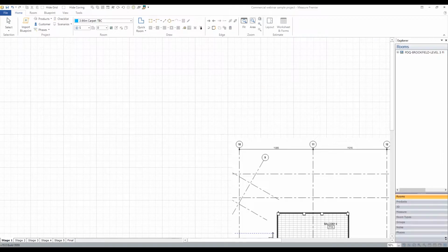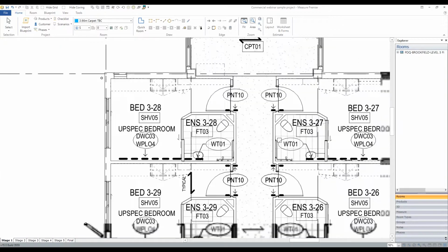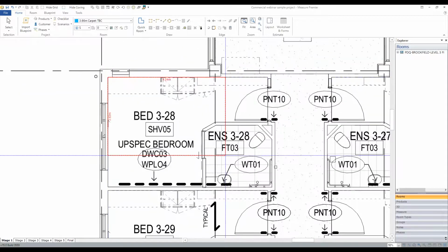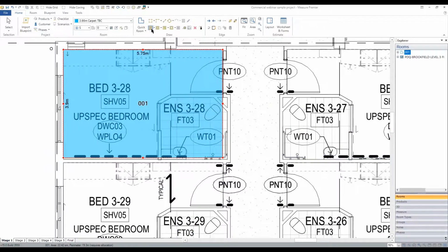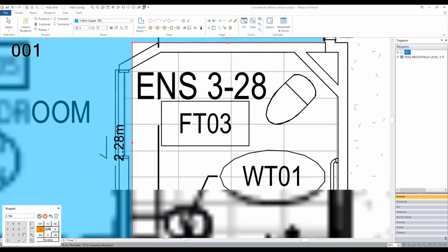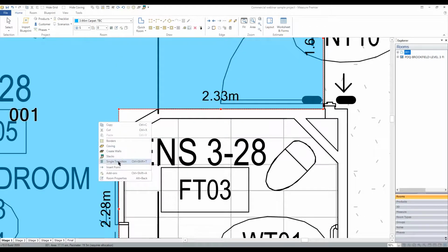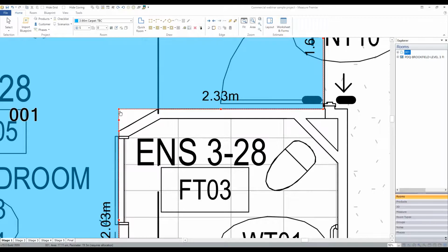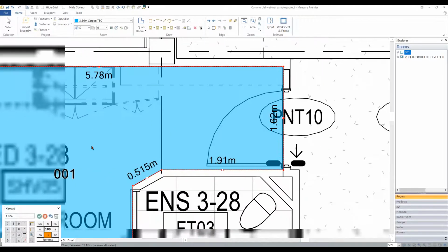So with all of our products created, I'm going to go ahead and start drawing up these rooms. We won't worry about what product is going into the rooms initially. We'll deal with that in a moment. So the way I personally prefer to draw rooms is start with a large rectangle, and then I will punch maybe a hole out to form that bit there. I'm not being very neat at the moment, but that's fine because I can just come back in and resize this a little bit. With a corner like that, I can insert a point and then pull this guy back over here. Right. Then you might zoom around the edges and make sure everything's nice and neat.